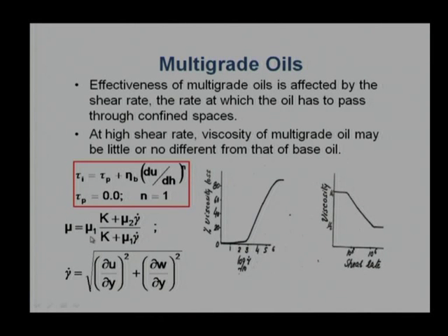If the shear rate is lesser than this limit, then it will be a high viscosity Newtonian liquid, and if the shear rate is more than this limit, then it will be a low viscosity Newtonian fluid. In between, in this example we are saying 10⁻³ to 10⁻⁶, but it is not necessary that every oil will be 10⁻³ and 10⁻⁶. It can be different. Now, if I use a high shear rate, the relation will always turn out to be equal to the viscosity mu2, because mu1 will be cancelled out, and if the shear rate is low, then it will be mu1. We can substitute and find.